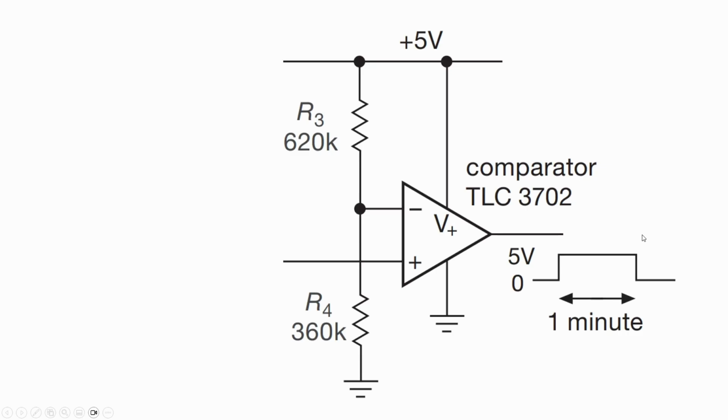Now let's look at the second half of the circuit. I think it's important to maybe start looking at this point over here. So we know this node over here is going to exponentially decay to 0 volts from 4.99 volts. This node is the non-inverting input and this node is the inverting input. When the non-inverting input is higher than the inverting input, your output will be high, clamped to basically, or close to 5 volts, depending on the performance of the op amp or the comparator.